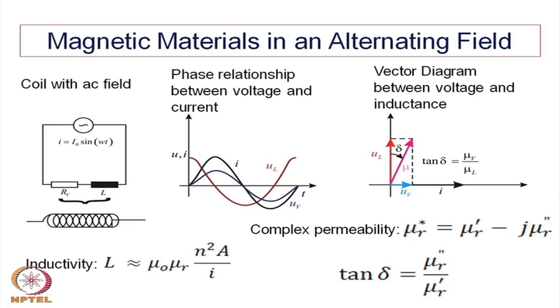So one has to understand how exactly they behave under different alternating fields of different frequencies. These are some of the additional parameters in addition to chi, permeability and the magnetic moments, but the tan delta values are also very important when you are trying to use them in different electronic circuits.